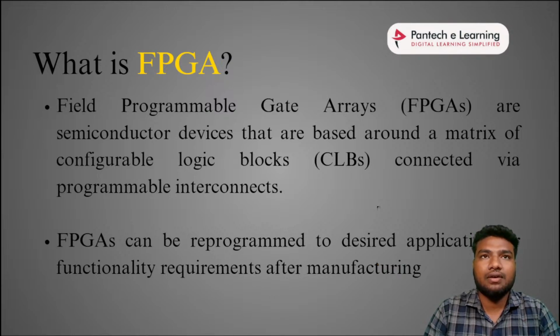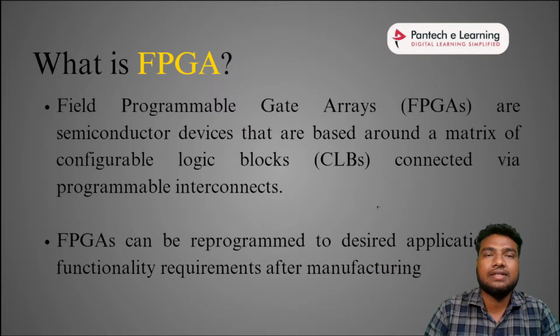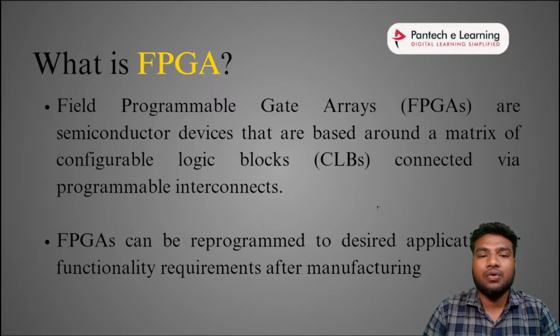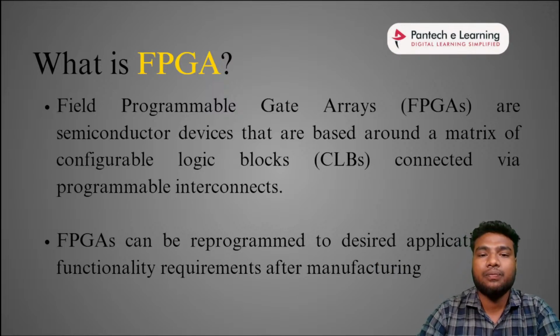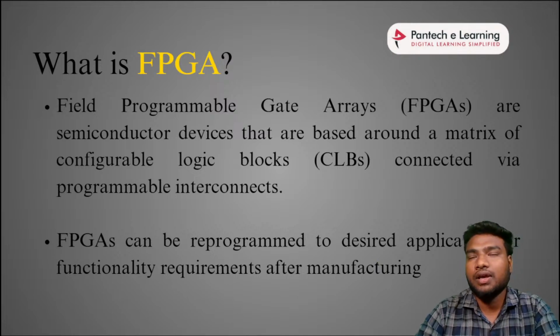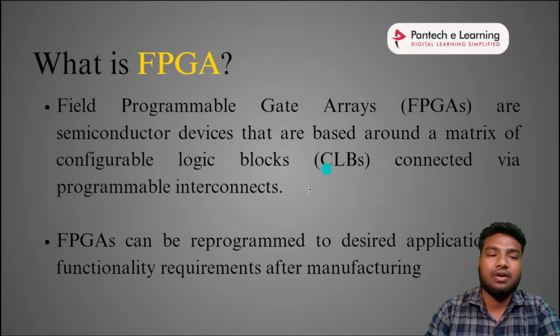It has a separate architecture and a separate logical element setup, like CLBs. An FPGA is filled with a matrix of CLBs. If you look inside the FPGA IC chip, you can find the matrix of CLBs. Each CLB consists of lookup tables, multiplexers, and flip flops. It varies from FPGA vendor to vendor. If you take a Xilinx FPGA, meaning Spartan or Zynq boards, those ICs have an architecture based on CLBs, configurable logic blocks.